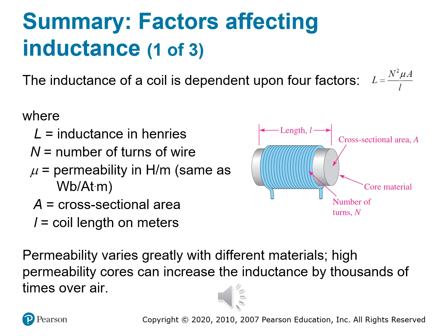And then L is the length of the coil, and again, that is also in meters. So let's go ahead and break that down even further. More turns equals more inductance because each loop of wire contributes to the total magnetic field, and inductance increases with N squared, and that's a squared relationship.